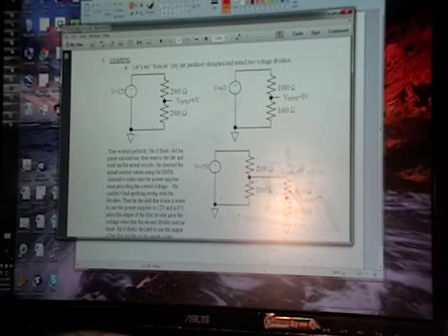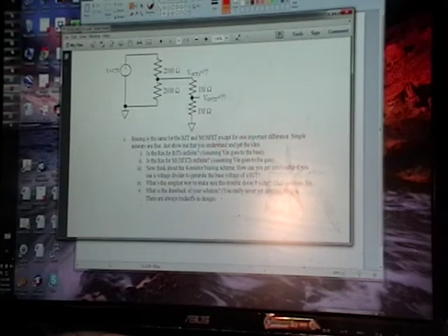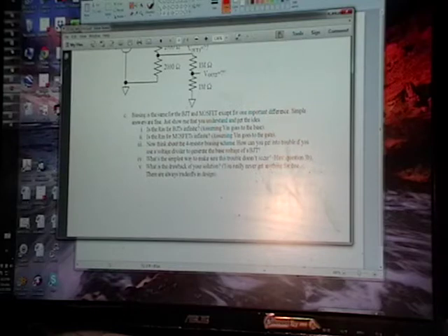And you get down to... we can talk about this a little bit more in class, but is the R in for a BJT infinite? No, it's not. Anytime you make a circuit that creates a voltage that goes to the base of a BJT, that BJT is going to take a little bit of current off your first circuit, so let's try that a little better.